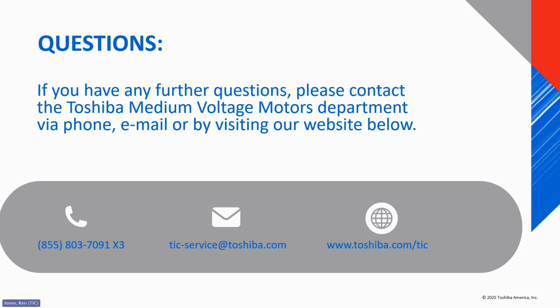The benefit of a wound rotor machine is you can actually exceed that by changing the slip within the rotor and the stator, where the voltage and frequency is adjusting the output on a VFD to 60 hertz. So there are some benefits with regards to wound rotor machines, and that's why they're still being used, for example, in conveyors and in ball mills, because you can actually benefit by changing that slip within the rotor.